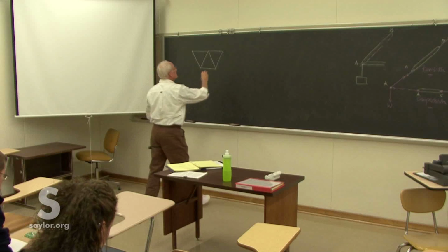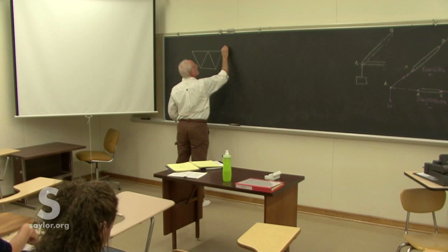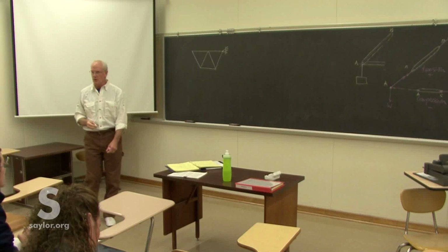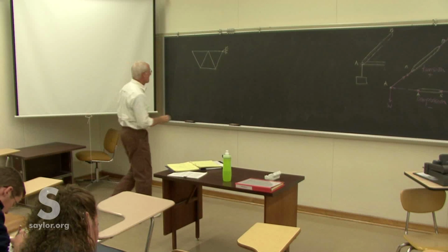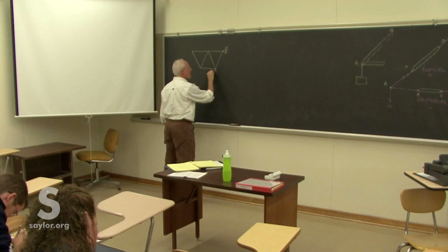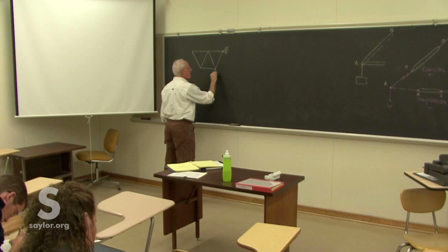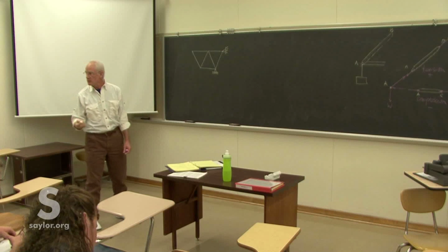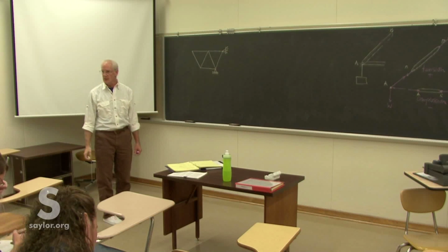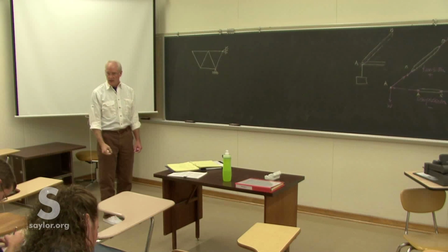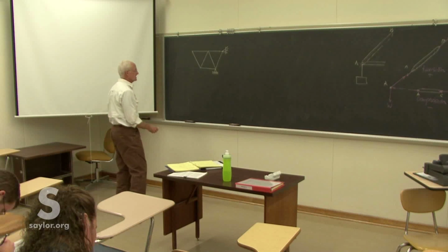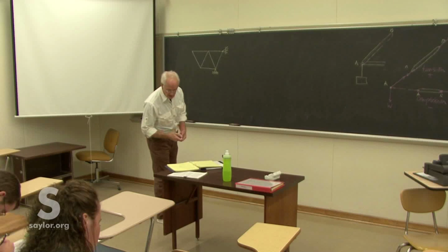So we've got this structure and it's pinned in support at one corner. Has a roller support at the other corner. Very same type of thing we were doing with those simply loaded beams. We have to have one support that only has one force in it. Otherwise, there's too many forces in the problem for us to solve.